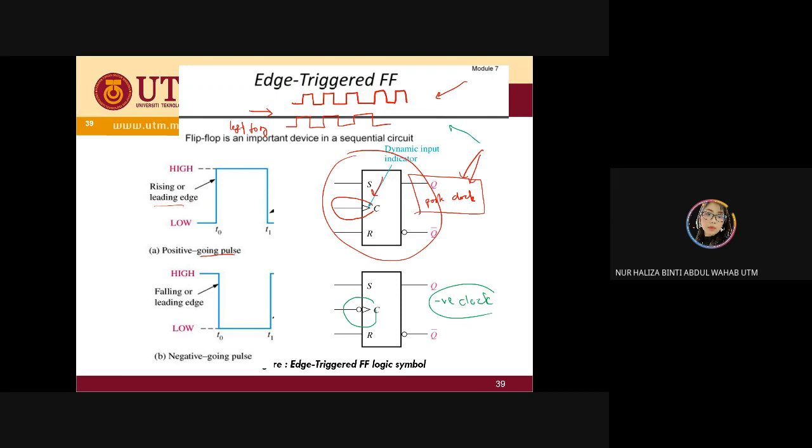But in the waveform also, because you were given the timing diagram, there will be an arrow pointing down, which is a move from 1 to 0, from high to low. It is not going to be drawn at this side, because it looks like it moved to the left. Instead, you need to point down, so it follows the normal movement of waveform from left to right. Okay, so that is about your clock.